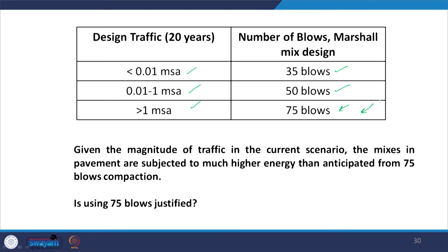And some of these studies have shown that for the mixture which you get using the Superpave gyratory compactor, the orientation of the aggregates inside the mixture is similar to what you get when these mixtures are compacted using standard rollers. So, with this thought process or this question related to compaction, let us now move ahead and discuss the next parameter, that is air void.